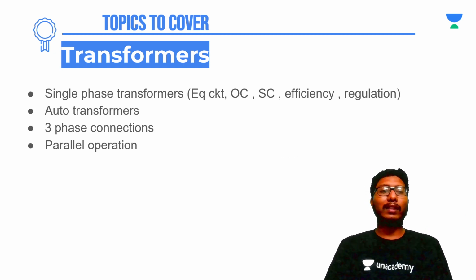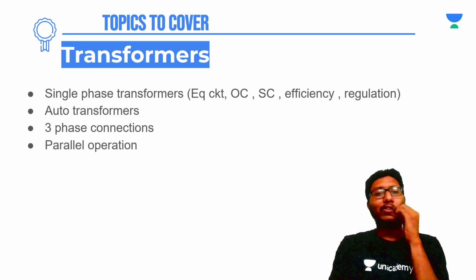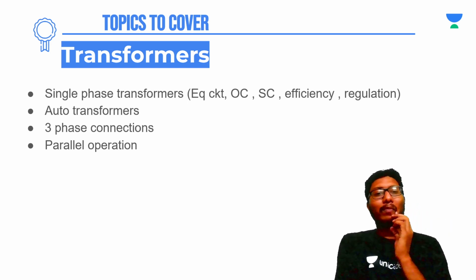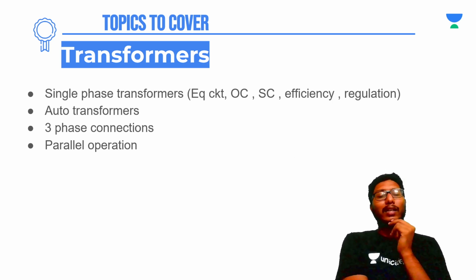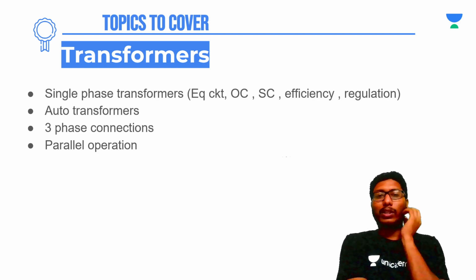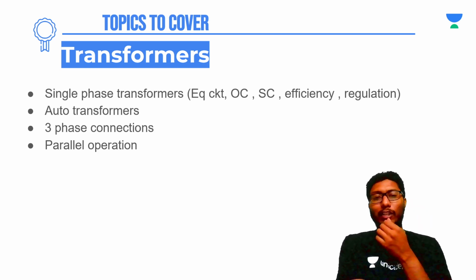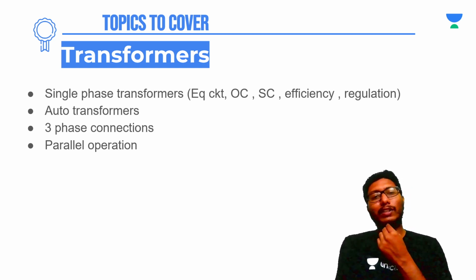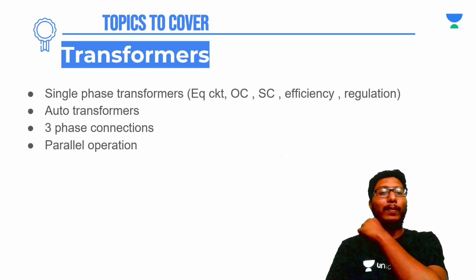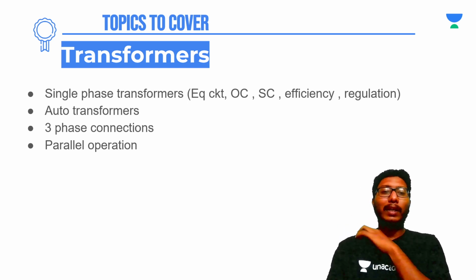And from this no load power factor you will get theta, and from this you find sin theta. Whatever power loss is given, power loss will occur across the resistance only, not across the inductance. So the shunt resistance, or no load resistance, of the transformer you can get from this, that is V naught square by P naught, and the magnetizing current is I naught sin theta naught. I naught is already given in the problem, and sin theta naught you have already obtained. From this you can find Xm, that is V naught by Im. So now we have obtained both Xm and Rm.